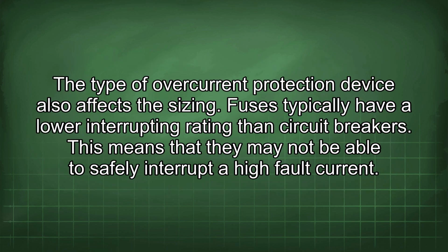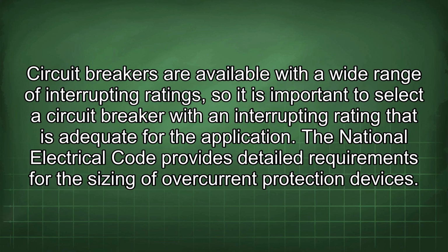The type of overcurrent protection device also affects the sizing. Fuses typically have a lower interrupting rating than circuit breakers. This means that they may not be able to safely interrupt a high fault current. Circuit breakers are available with a wide range of interrupting ratings, so it is important to select a circuit breaker with an interrupting rating that is adequate for the application.